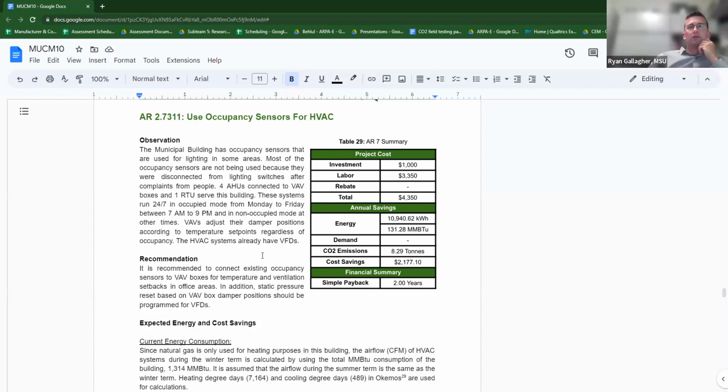Oh, so yeah, it triggers less air circulation in there, whether it's heating or cooling, depending on the time of year. But let's say we're in a heating cycle and we're heating the building in the winter, that warm air is going to bleed over from the office next door because we don't have any insulation in our interior walls. So I'm just wondering how impactful can the VAV be in a facility where you don't have that interior insulation?